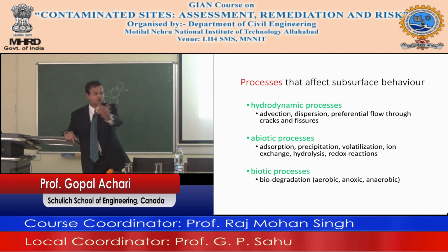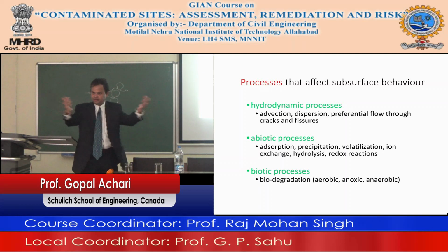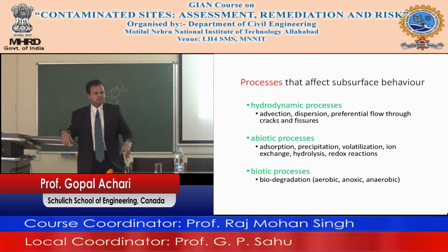You deposited it as a bag at one location, but you will find it all over. The fact that it has moved all over is because of dispersion. There is a velocity-driven part, which is advection, but the horizontal part is dispersion. Are you with me on that?